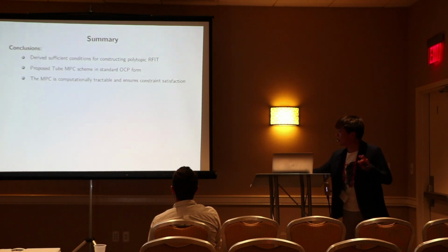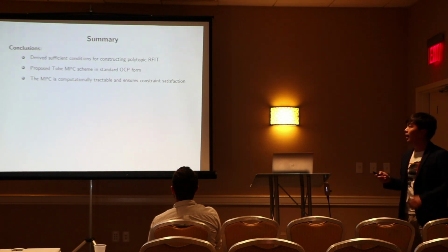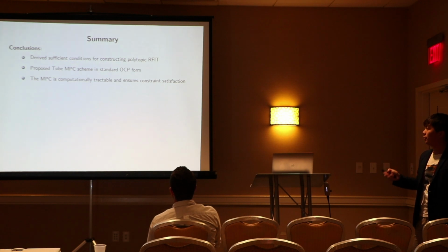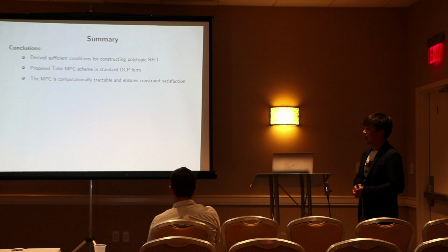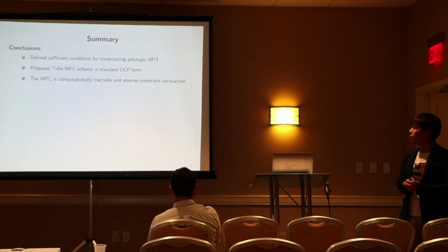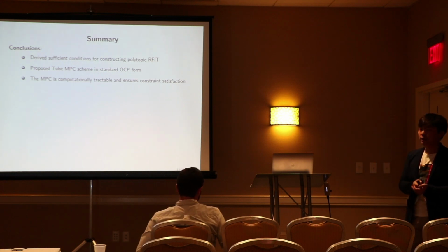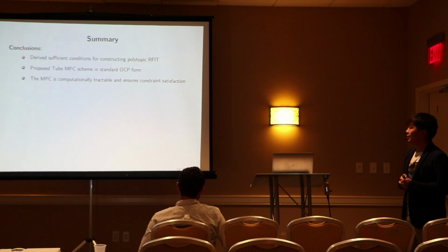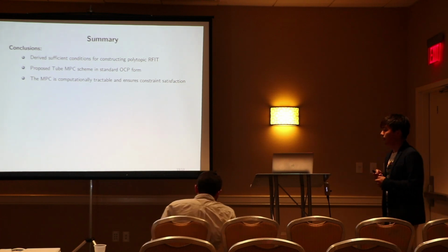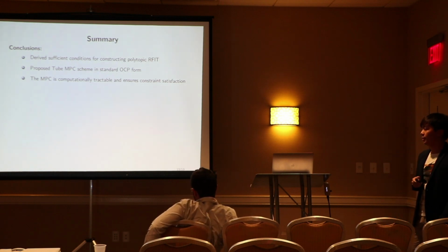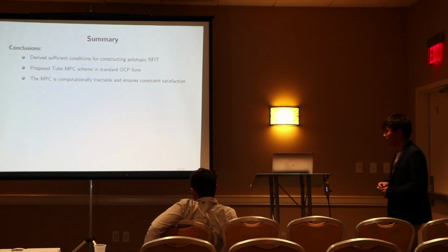So as a short summary, we have just derived sufficient conditions to construct RFITs that are parameterized by polytopes. And we also provide a tube MPC scheme based on that, which is in standard optimal control problem form. So it is computationally tractable and ensures constraint satisfaction for a closed-loop system.